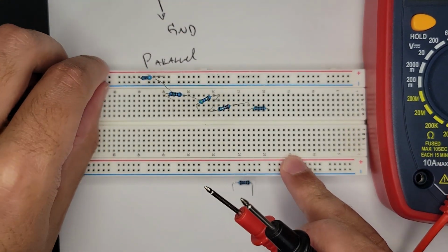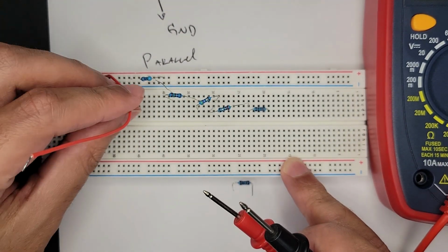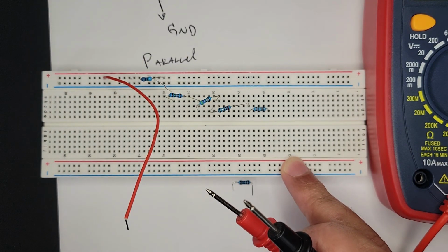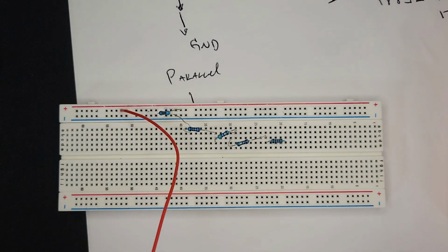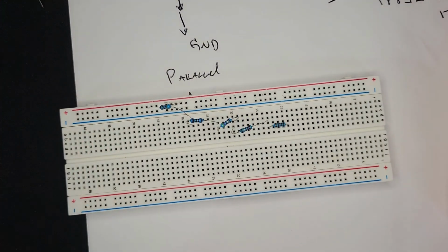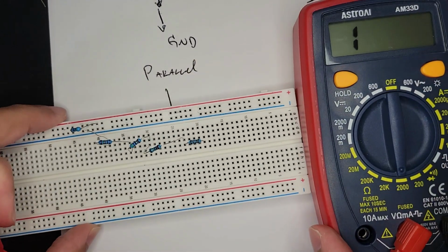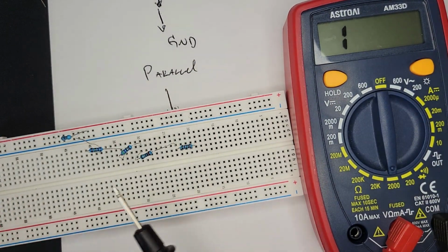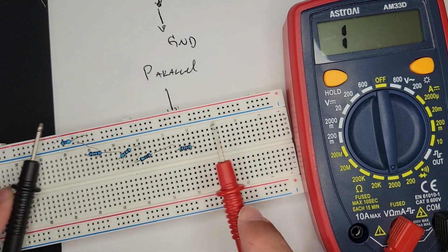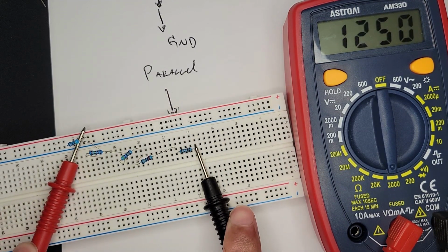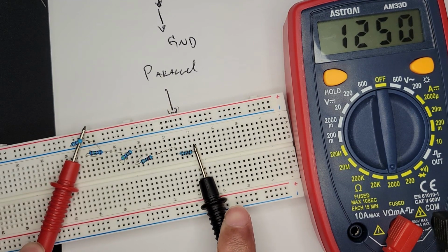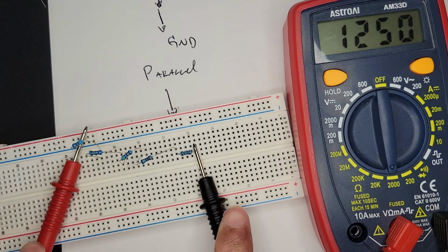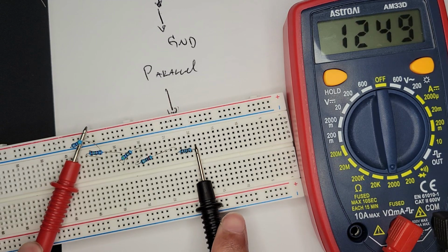So now I'm going to make sure my power is all unplugged, and it is on the opposite side. You can see here. Oh no, I just broke this. So our power is unplugged, and let's take this resistance reading from one end to the other, and we can actually measure all of the resistance. So we can see our total resistance here is 1250. I don't remember exactly what we used. I know we have two 47s, I think a 22 and a 100, or a 150, and then a 1000. But what seems to be happening is we have 1250 total. So this is a very convenient way for us to test all of these. They're in series, and you can actually just take the resistance of the entire circuit.